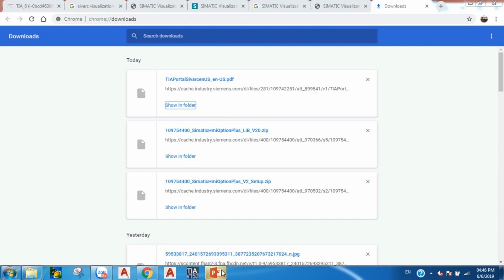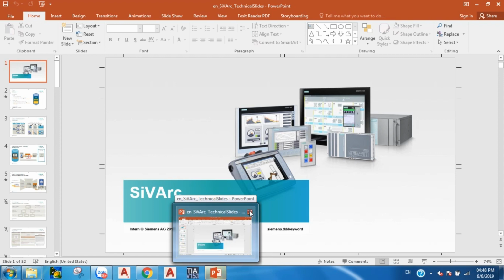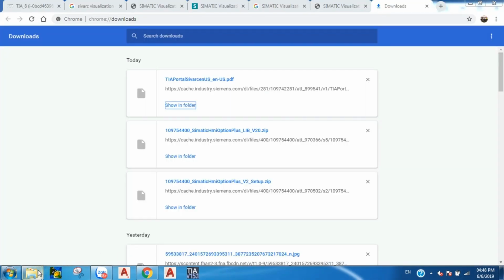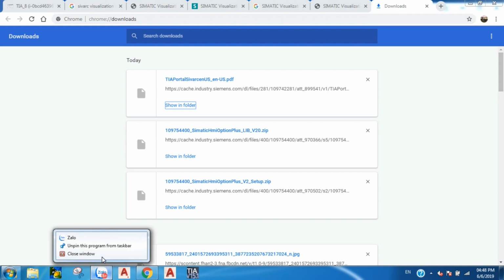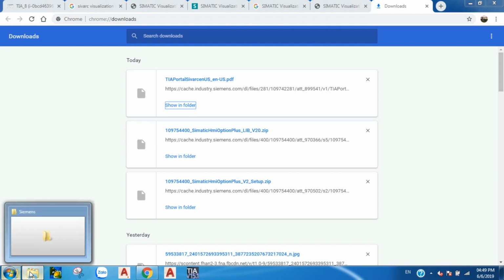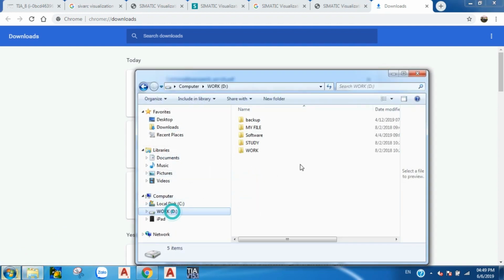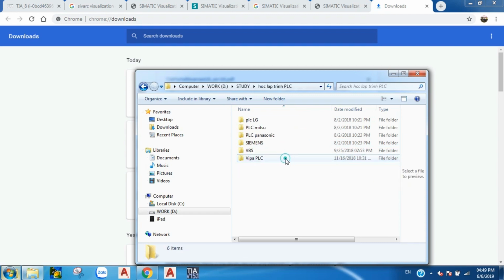So I switch back to my screen modes because I want to place another object on the screen. I create a new screen mode. But this time I don't want to use my singleton, because I want to have just one trend control, which includes the trend value of my FB tanks. So in this case, I choose my FB tanks. And for my screen object, I want to use the trend view, which is located in my master copies under CWARP, Trends, FB trend view.